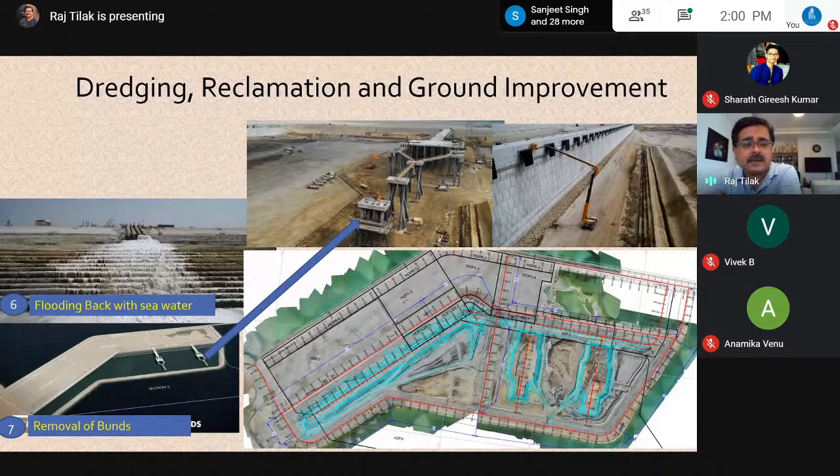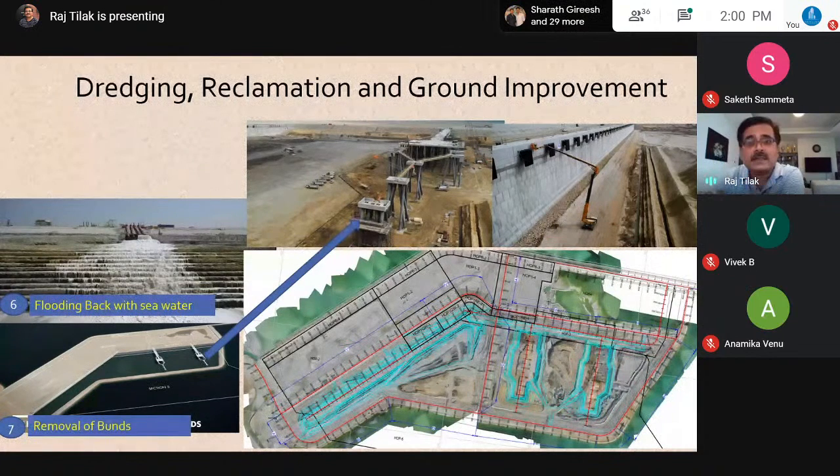And imagine building a raker pile from the ground and having something connected at the top with perfect alignment. When you do it from the top, it's much easier because your top structure is aligned. But here you are constructing something from the bottom and you are expecting it to align properly at the top. So there are challenges that you will face.